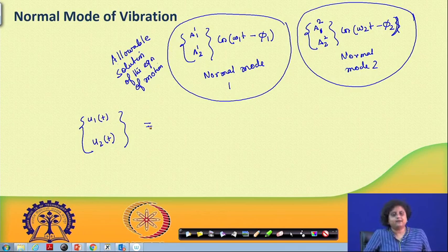Okay. So, if I have any 2 degree of freedom system, or to say any n degree of freedom system or any multi degree of freedom system, I give them any initial excitation possible, any initial value of displacement, initial value of velocity, then I can always say that the response of any arbitrary system under any given initial condition can actually be written as a linear combination of the normal modes of vibration. Because this is a very important concept, I would like to emphasize on this.